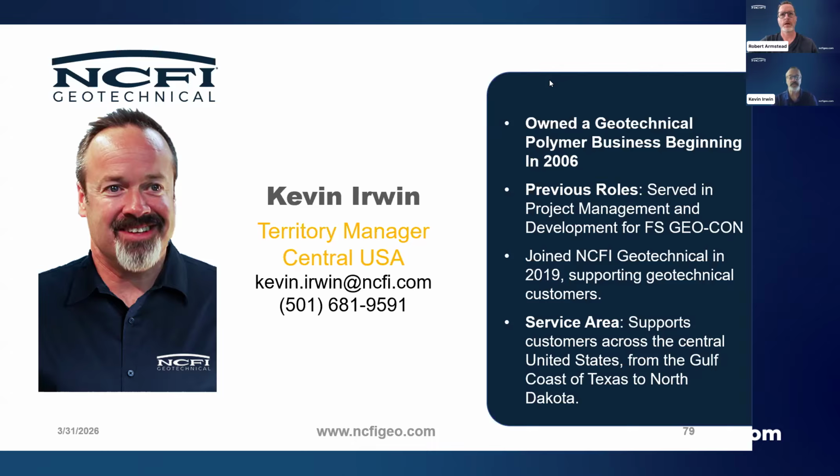You really got to watch for that stuff. Yeah, and I think beyond that too, it depends on the goal of the project. If you've got cracks all over your seawall or bulkhead, or loose joints, and one of your aspects is to seal those cracks or joints, you're going to get travel, and you're going to want a second pair of eyes continually monitoring the water flow, looking for when material starts to float or when they get a sheen or anything along those lines, because that is showing that the material is permeating through somewhere.